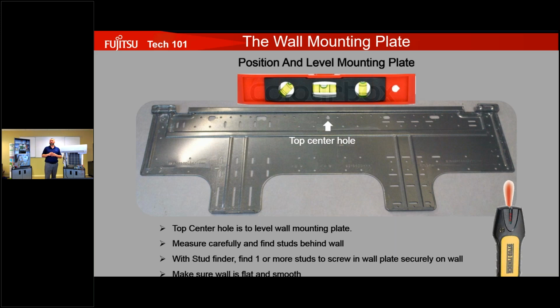Another thing that they don't really point out so much here, a couple of things that I've noticed. I came directly from the field. I've installed hundreds, if not thousands, of these wall-mounted units. There's a couple of places where we have stress points over the course of time and realize the best places to put our screws. So we always want to try to find at least one or more studs when we're mounting the plate. But even more so than that, we want to cover the stress points of the unit.